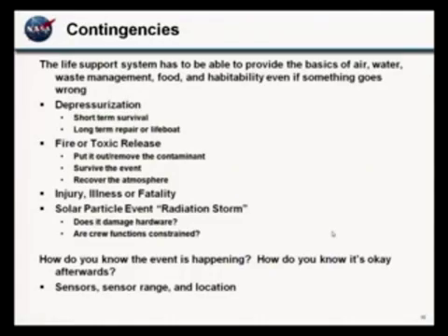You also have to think about where you place these things when we talk about how many different volumes we are conditioning and controlling. You don't want the smoke from a fire to be ventilated across three modules before you detect it with your sensor, right? You want those placed close to where the event might happen. So those are just some examples.